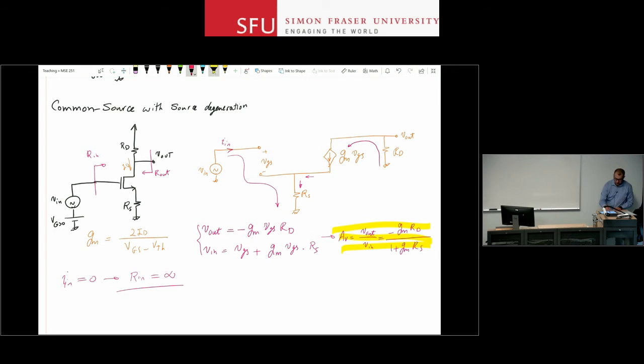Well, that is nice, right? Remember, for a voltage amplifier, we wanted a very large input resistance. There is really nothing larger than infinite. There is really nothing that draws less current than an open circuit. It's zero current. So with a MOSFET amplifier used in a common source configuration compared to common emitter, you lose some on the gain, but your input resistance is essentially infinite. So that part is very valuable in a lot of cases.